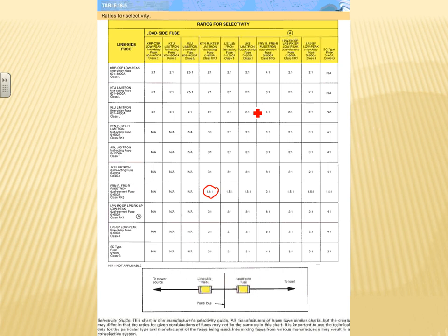Besides the hospitals that you mentioned, we don't do a lot of hospitals, but if you have more than one elevator on a common feed, you have to coordinate them. Elevator protection devices against the one serving the feeder. So that can be a little challenge.